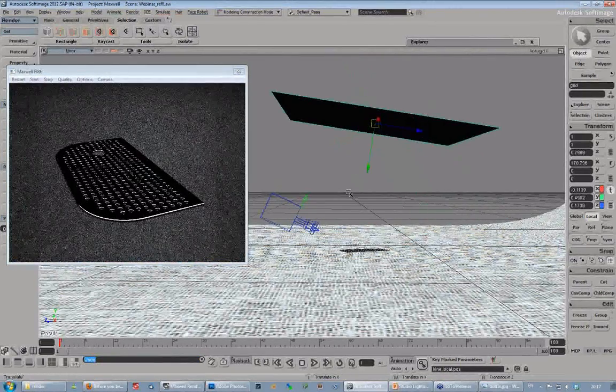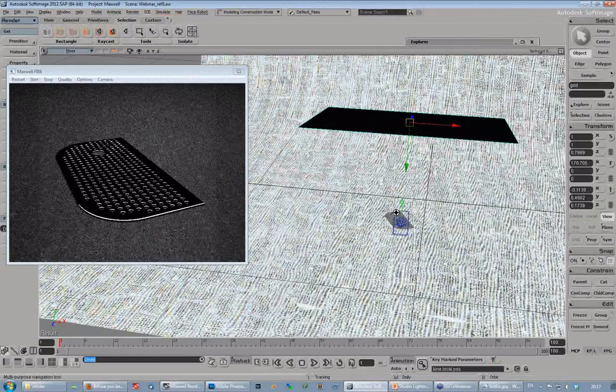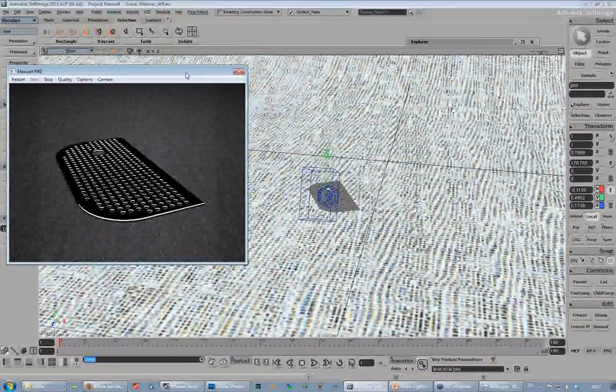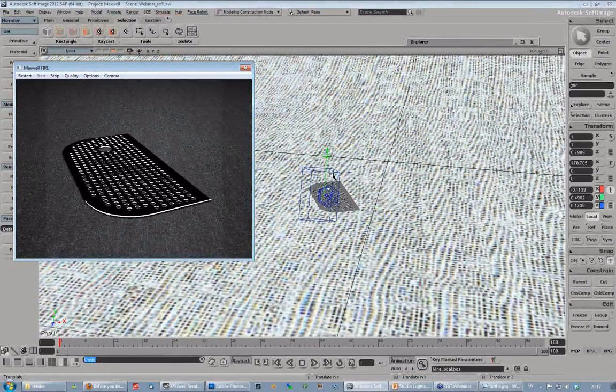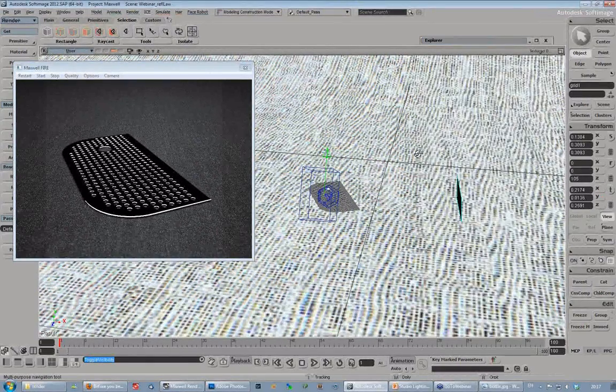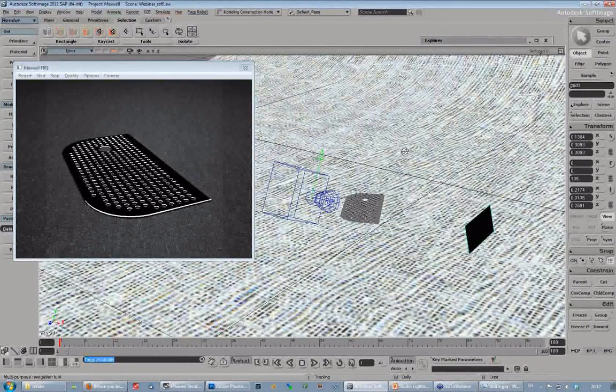Now, in this scene, for example, I have in the backdrop here a cloth material, or it's supposed to be a cloth material, but you don't really see the bump in it. So one tip I can give you is when you want to bring out the texture in something, like cloth or any kind of texture, use a smaller emitter, and place it below that surface.